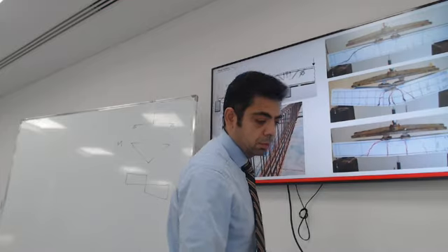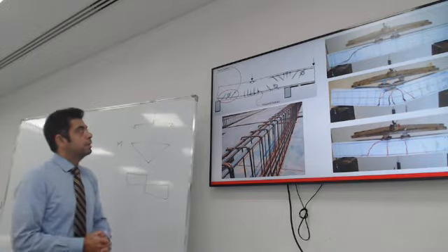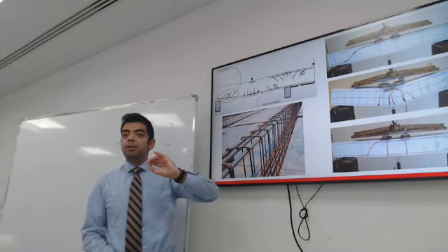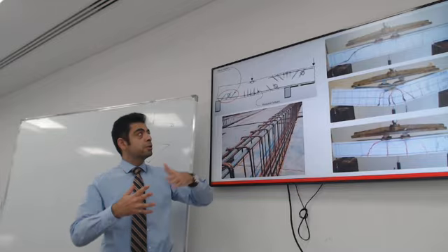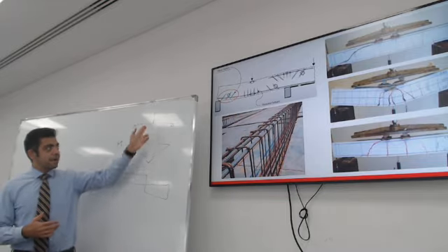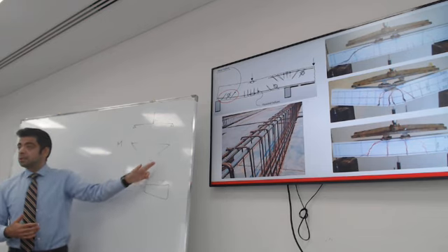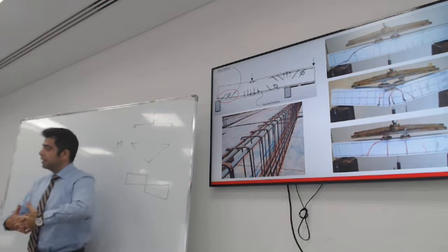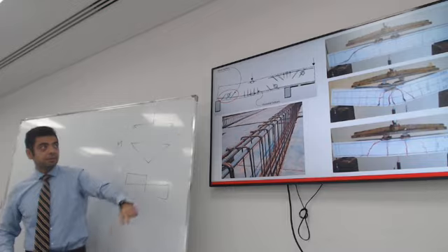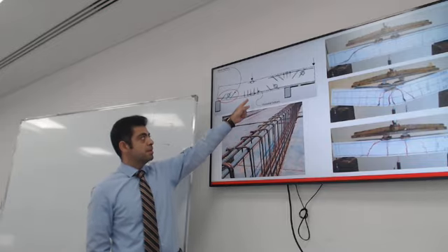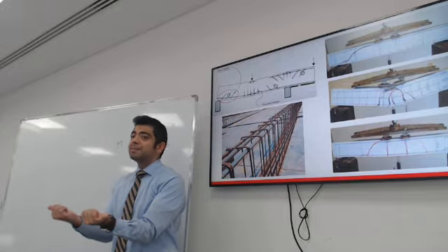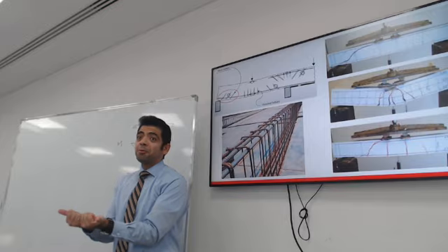So, how do you overcome these shear cracks? Last week, we talked about how we reinforce the flexure cracks. The bending is maximum in the midspan. This is where the bottom vertical cracks are going to have maximum effect. That's why they are in midspan. Most of the tensile forces are resisted by the bottom reinforcement.